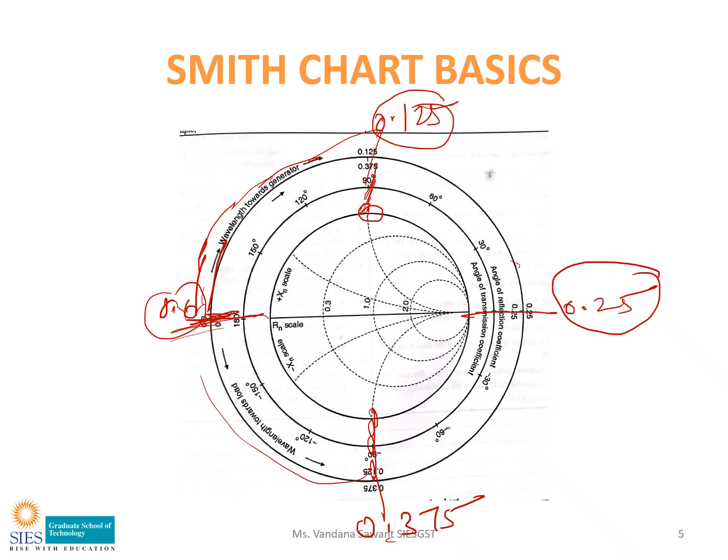If you go over this circle, whatever circle you get after connecting all these points is called the wavelength circle. If you want to find the wavelength at any point, you just draw a straight line from the center through that point and out of the graph. That line will intersect the wavelength circle, and where it intersects is the wavelength for that point.